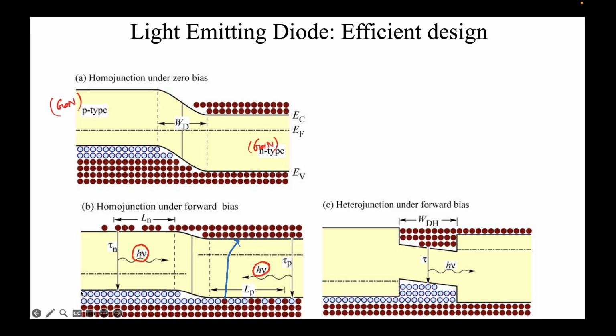So this material is some unknown material X. On this side also the same material X. This is gallium nitride in the middle. So what you see is that an electron and hole will recombine, something like this. A photon will be emitted corresponding to this band gap. So let's say this band gap, we know it's 3.4 eV for gallium nitride.